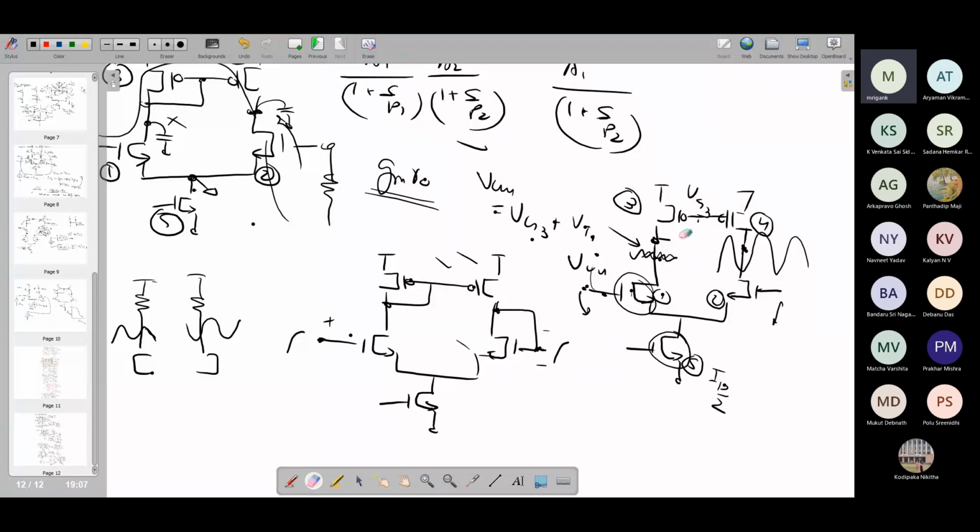That is not deterministic, right? First of all, in this case it depends upon what the output DC voltage is. So what is the maximum output DC voltage you can bias it for? VG3 plus mod VTP, right? So this maximum output DC voltage is basically VG3 plus mod VTP. And then if I assume this gate voltage can go higher than that by mod VTP, that will determine the upper level. Generally, of course, you will not keep this at the maximum value. Otherwise, on the upper side you don't have any swing. For maximum symmetric swing, you will probably place it somewhere in between.